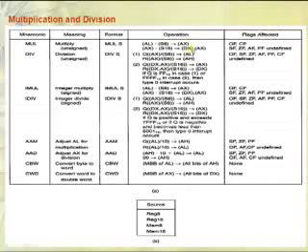The result is stored inside AX in case of 8-bit. If it is a word size, that is AX gets multiplied with a 16-bit source, and the result is stored inside DX and AX. And the division operation, again, does the division between AX and the specified source operand. So DIV S, source operand. It performs the division of AX by this specified source operand.